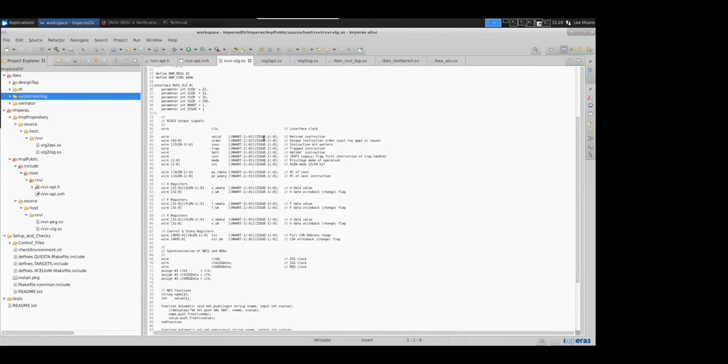So if we had a hart within a processor core which could perform 3 issues in parallel, then we can describe that in this format here. The intent is to describe the flow of the program as it executes and communicate out the values of the program counter, the values in the X registers, whether the instructions continue to execute to retirement or whether they cause traps, updating CSRs and things like that.